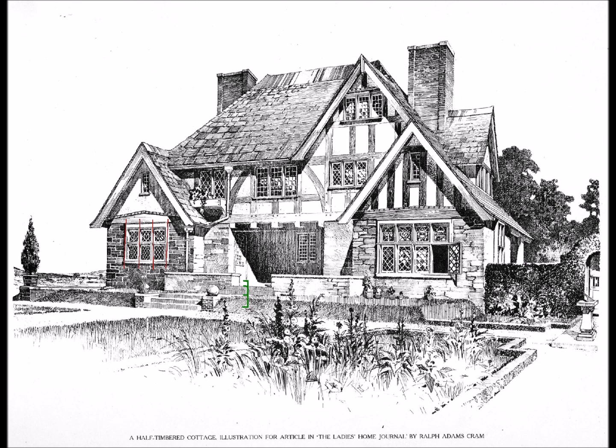The next thing we're going to do is try to get a sense of the overall size of the house in plan. So here by this window, I've drawn 3 red lines to indicate spacing. These windows appear to me to be roughly 2 feet wide. There's a set of small windows here and up here and a narrow window here. Those are a little bit different than the other windows, but the main groups of windows look like they're 2 feet wide. So on that basis, I'm going to make some estimates at dimensions.